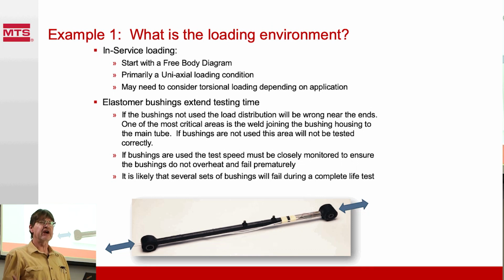What is the loading environment? Well, there's rubber bushings in the end, and the things can get pushed and pulled on, and they can get twisted, and they can get bent. How critical are the twisting and turning and bending compared to tension compression? That would be the first question we might want to ask, and we can answer that question by doing some instrumentation and measuring some of the loads.